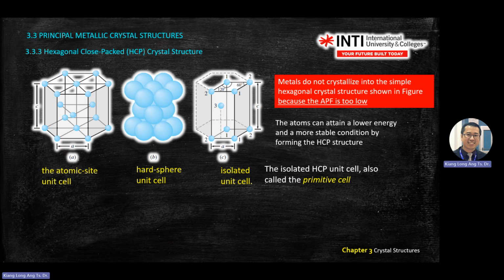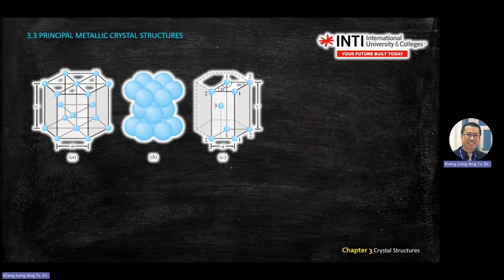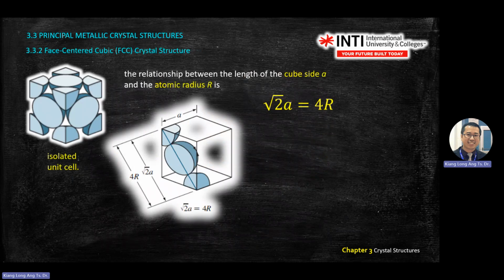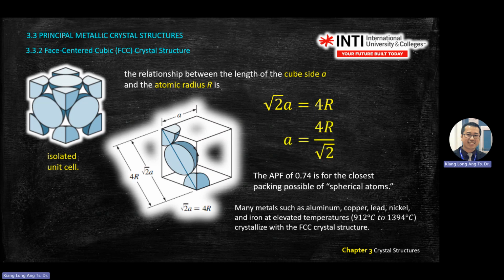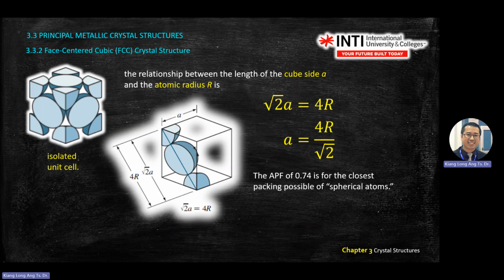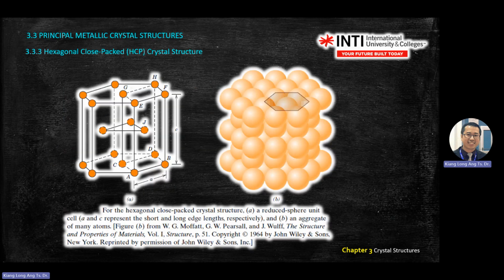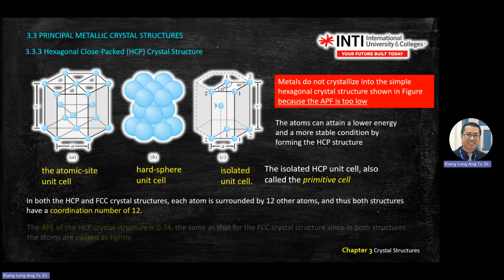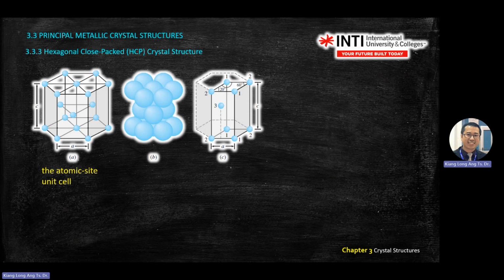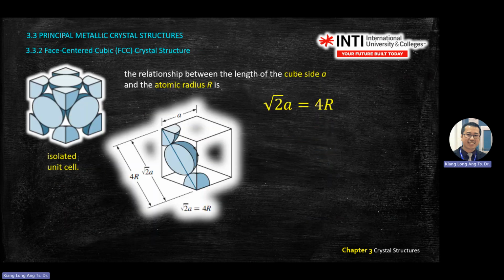Okay, maybe I'll show you the FCC. Okay, this one. If you focus on this atom, this sphere, this is 1/8, right? So actually on the top you have 4, here also 4. Let me show you, we want to show that the coordination number is 12, this one. Coordination number means the sphere is in contact with 12 atoms.